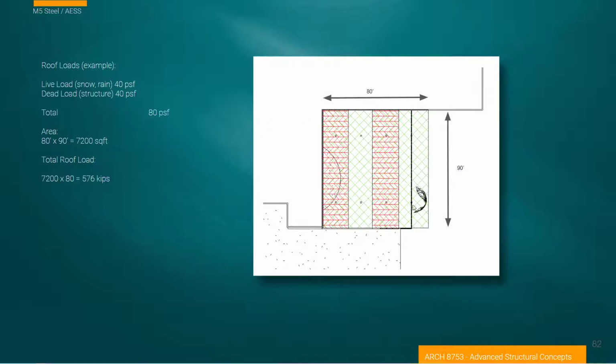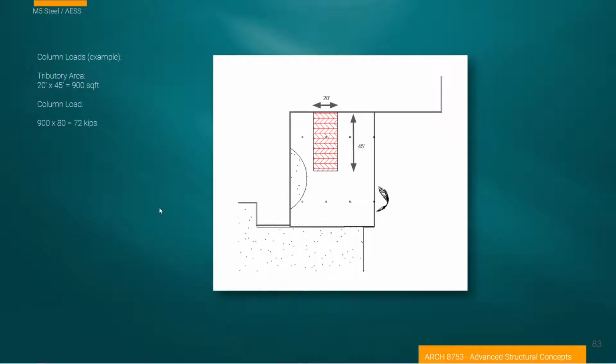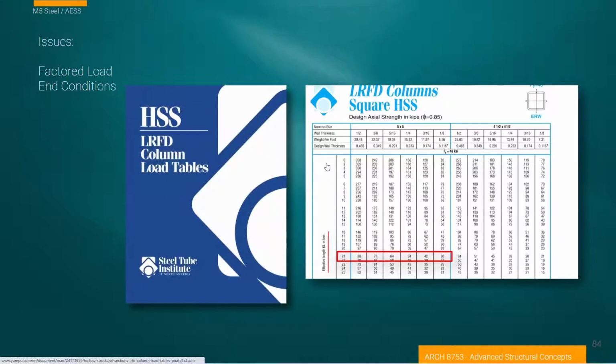So here we have a roof view of that. We have the idea of live loads and dead loads applied on it and coming up with a value system, and then taking its overall tributary area to come up with a total load in that area. And then taking another look at that roof load, specifically as it's carrying down through the column systems as a tributary load. And we can do a lot then to figure out the sizing of certain elements, especially things like columns, where we care about how large they look and whether they have capacity.